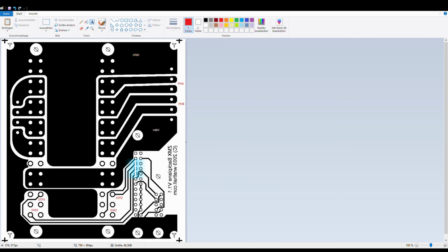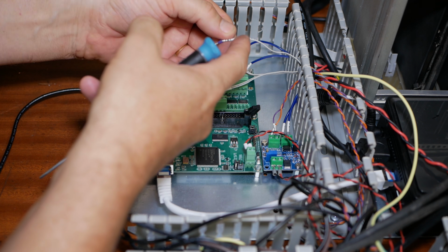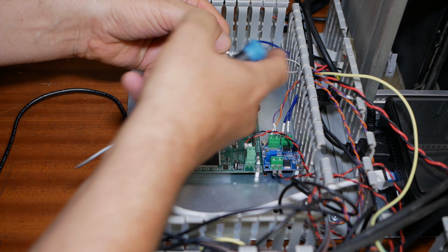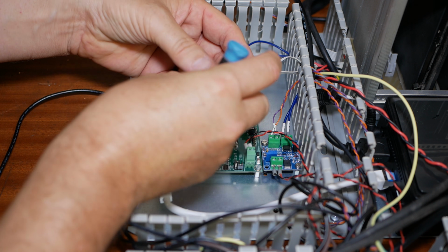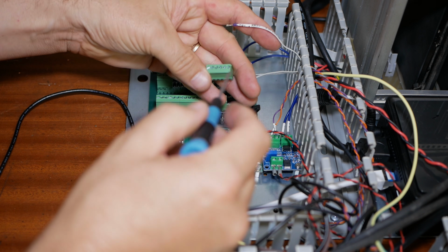So really I've only got these 4 wires to connect into. So I'll probably just butcher my existing ribbon cable and just break out those 4 wires. Each individual wire that I'm using, I've kept it paired with another just to provide a little mechanical stability to it. So this connects to TB14.